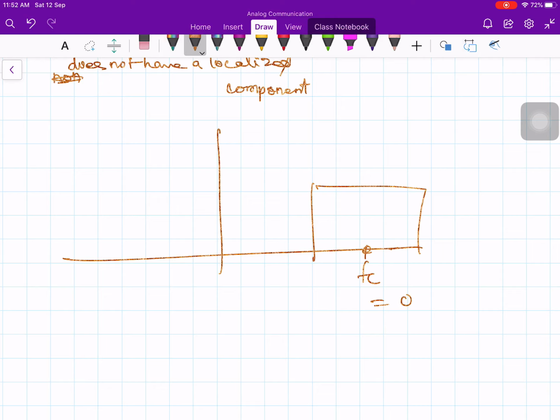Okay, so in this there is no carrier component. No carrier component means no impulse. If you don't have any impulse, then you cannot say there is a carrier power explicitly. But you can ask me, there is some value of the spectrum at that frequency surely, but that value will not be a carrier. It could be 0, because it is a density function. At a single point you cannot say this is the value.